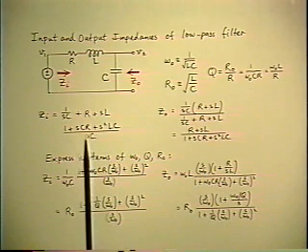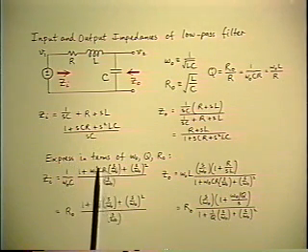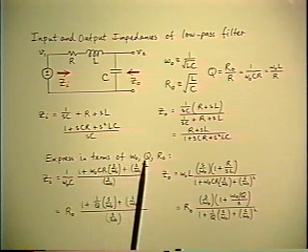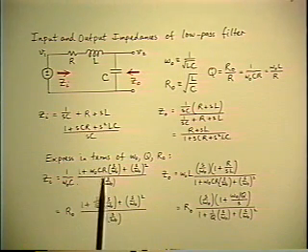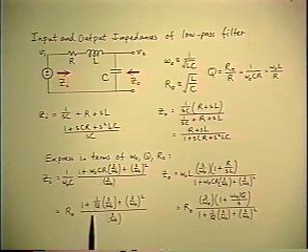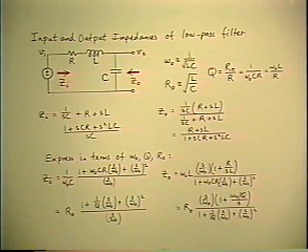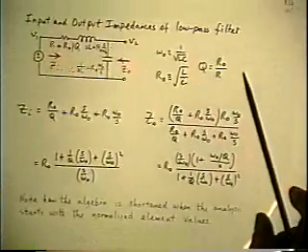And then you want to substitute the same normalizing quantities that we used before, namely the omega 0 corner frequency, the Q factor, and the R0. So when you make those substitutions, you can collect the final result into this form in terms of the normalized quantities. And once again, that's a long way around for doing it. And this allows me to make a new principle here about how to minimize the amount of work that you want to do, which is: start over.